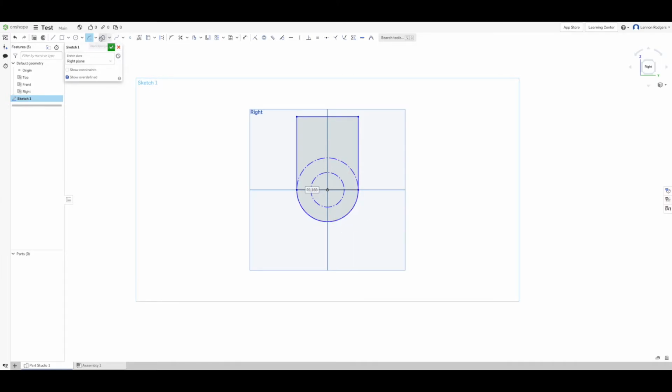And you can go through the different options. There are a lot of different ways depending on how you want to create that arc, and so they all kind of do the same thing depending on what your intent is. And then I'm going to come back here and actually, I changed my mind, so I'm going to put that back to a solid line. So it's actually going to drive geometry. So you can see here, one is kind of hidden, and one is solid.